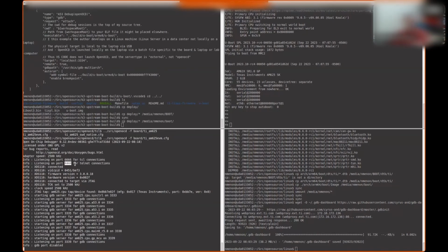Another place this is useful is when you are debugging the memory MMU tables. For example, R5 has something called RAT, which is essentially an address map table, which is kind of cheap because R5 by default doesn't have an MMU. So your physical address table, which is in the 64-bit address space, now needs to be mapped to a 32-bit address space. So we use RAT to do that remapping for the R5 processor. We do the same for M4 as well.